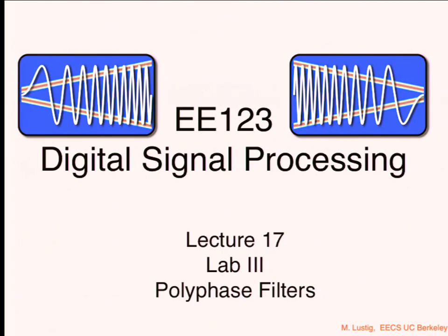The main purpose of that problem is really that you go through mathematical derivation and see that you can reduce the noise quite a bit using wavelet thresholding. And if you compare that to just low-pass filtering to achieve the same level of noise, you barely touch your signal, whereas if you did low-pass filtering, your signal would look very different than what you started with. So even though you reduced a lot of noise by low-pass filtering, you really also removed a lot of your signal. While with wavelet thresholding, you barely touch the signal, but you remove a significant amount of noise.